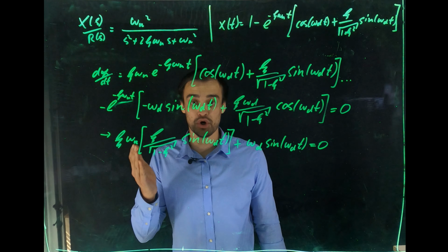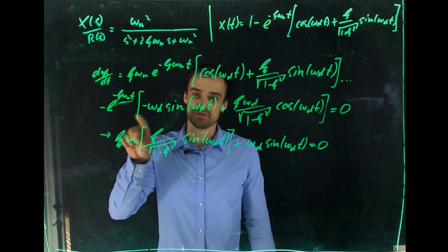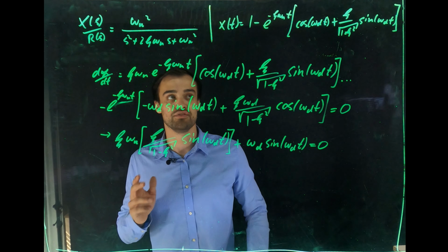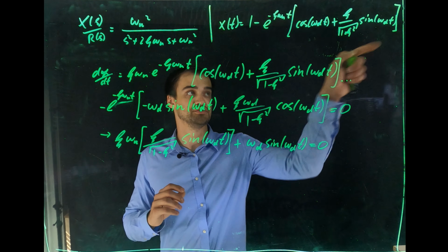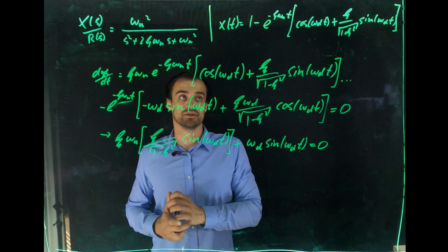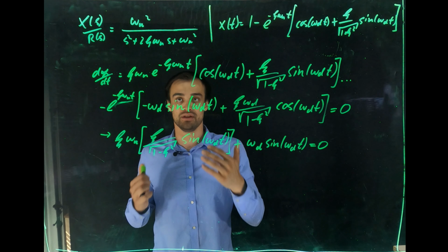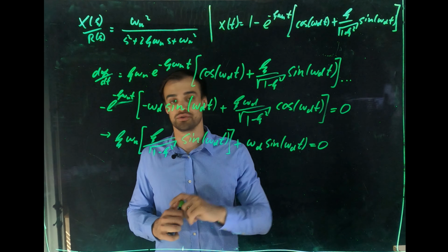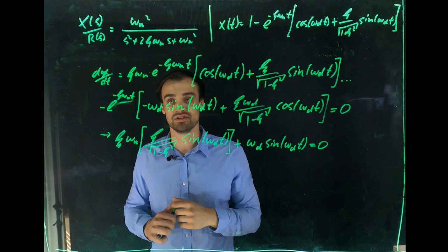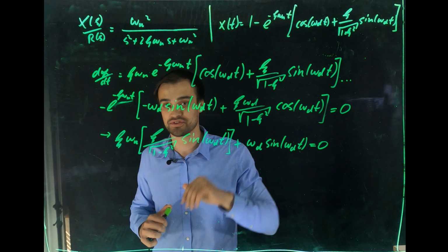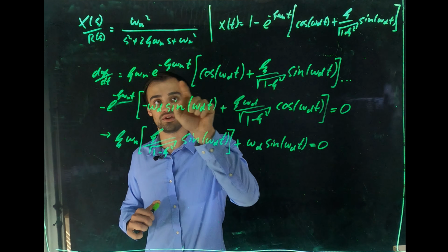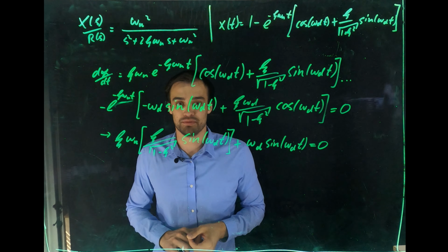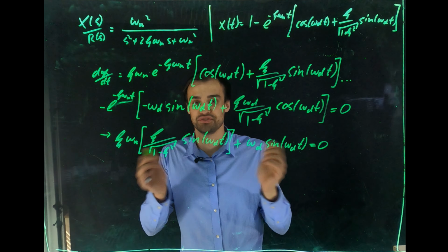For the peak time, we know that the system's output derivative has to be equal to 0. Therefore, I'm taking the time derivative of this function and writing it down here. Of course, you have to apply the product rule, first on this part, and then you can take the derivative of this part. What we can see right away is that the 1 is a constant and falls out, and this one and this one are common. You can make further simplifications to arrive at this equation.